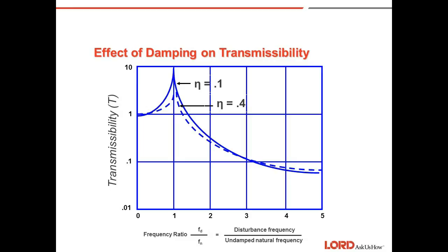If the disturbing frequencies are known and adequate sway space is available, a lightly damped mounting system with a natural frequency well below the disturbing frequency would be selected. But in cases where the disturbing frequencies are numerous, unknown, or impossible to avoid due to sway space limitations, a highly damped system is preferred. The high damping reduces the peak response that can occur if some disturbances are near the natural frequency. However, other performance properties may be compromised.